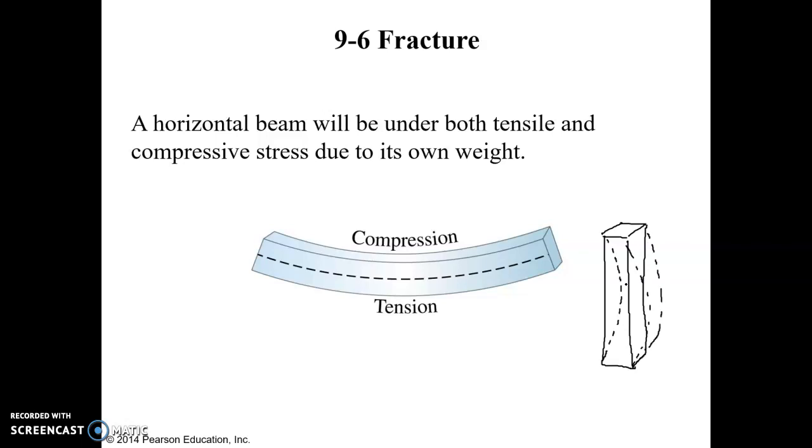And if you think about it, the buckling of a column to the side is no different than the bending of a beam. A beam is laying down on its side already, typically is loaded in the vertical direction, and that causes bending to occur. Now, bending stresses are actually a combination of several other types of stresses. You have compression at the top.